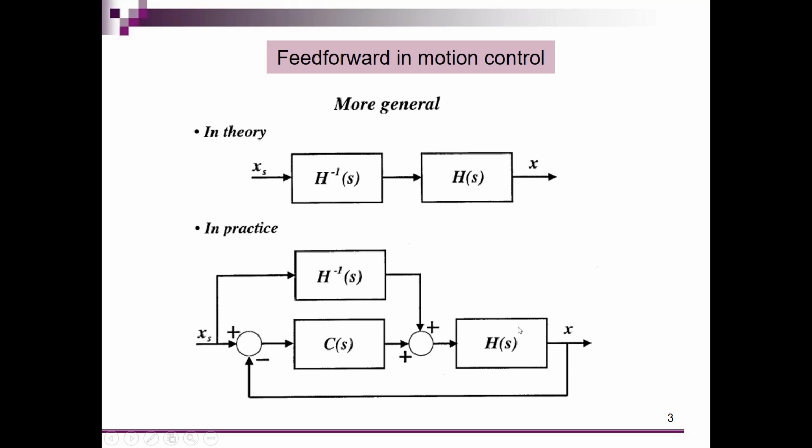So here you see the standard feedback controller, and in addition to that feedback controller, we designed and implemented a feedforward controller over here. And here we see one of the biggest advantages of a feedforward controller. This feedforward controller is completely out of the feedback loop, so it does not have an effect on system stability, and that's really nice.